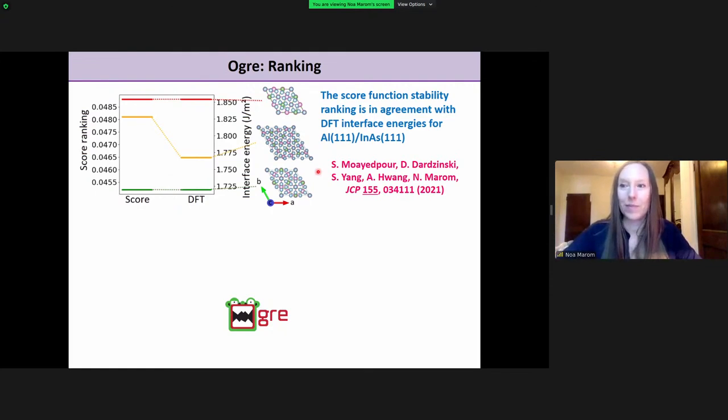One small thing: when you talked about this in the last section, about this need for very large layer count, in my experience, if I make my cell really large, I get really problematic convergence behavior, at least with VASP. I'm not sure what codes you use, but this high asymmetry of the cell is not playing really well with the code, it seems. So do you see something like this, or is there a way to correct it?